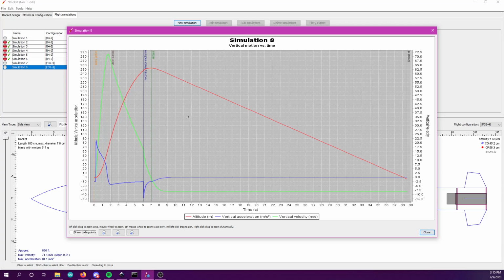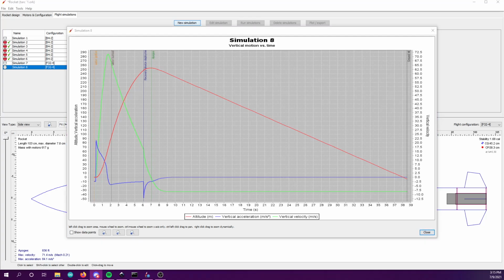There's one problem here. Well, not much of a problem, but something to consider. Our parachute is being deployed a little early. Typically, we want the parachute to be deployed, roughly speaking, a second after we hit apogee, so on its way down. Right now, it's deploying on its way up, which is not great because it's inconsistent.